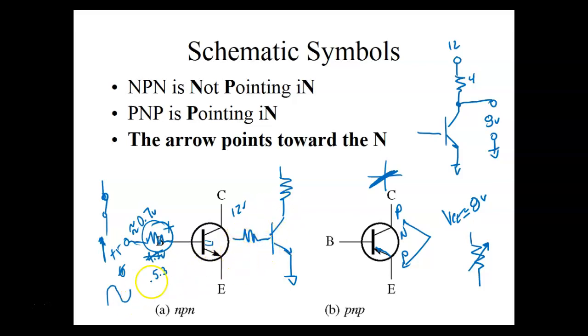And then I would come over here. This can't be AC, by the way. And we'll talk about this later, because if it was true AC, every time it went negative, the transistor would cut off, right? You understand? So what we'd have to bring in, if this was 0, is something like this. When this is DC, it's just DC changing at its AC rate. So it would be like we did before.